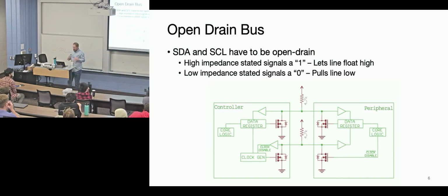The benefit here is that you could have two systems that have different voltages. Say this one was at 5 volts, and this one was at 3.3 volts. As long as with the VDD here, this pull-up resistor, both are tolerant to that, then they can talk to each other. So this is a way to have kind of voltage-invariant buses. There are some details to keep track of.